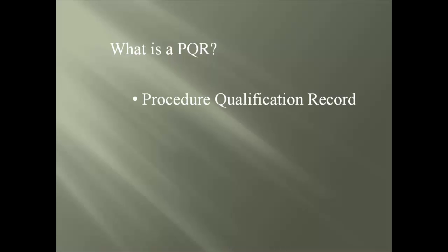First, let's start with the basics of the PQR, and that is to answer the question of, what is a PQR? Okay, the letters PQR stand for Procedure Qualification Record, and this is a living document of the actual welding variables and test results that were used to produce an acceptable test joint.